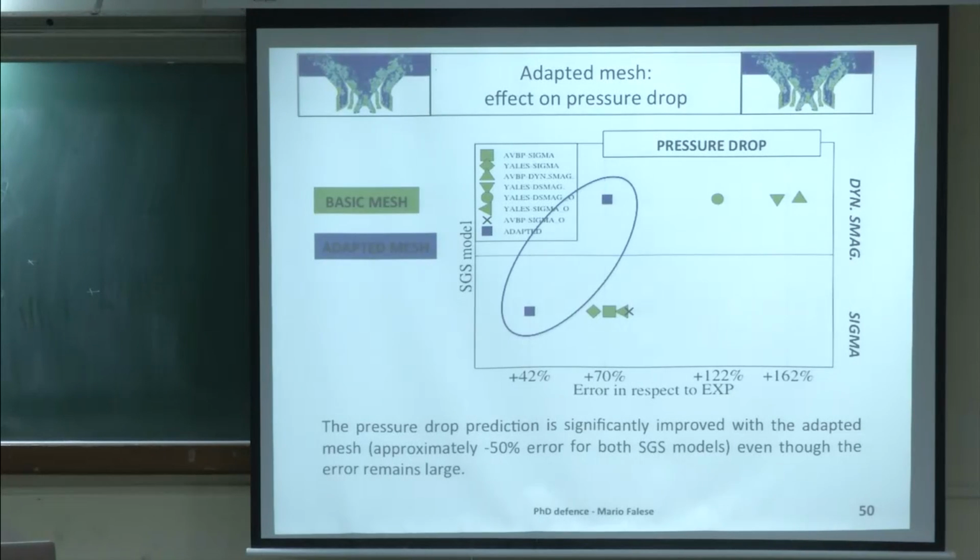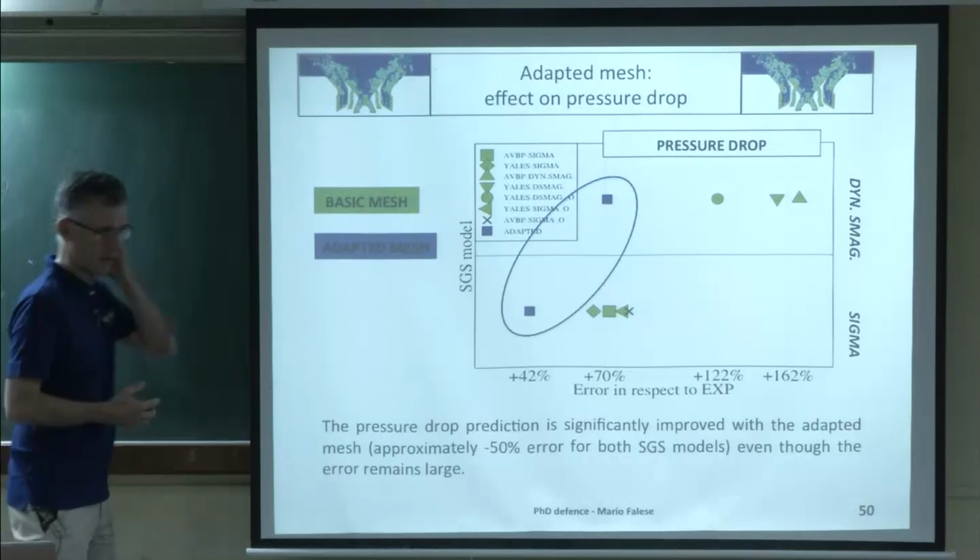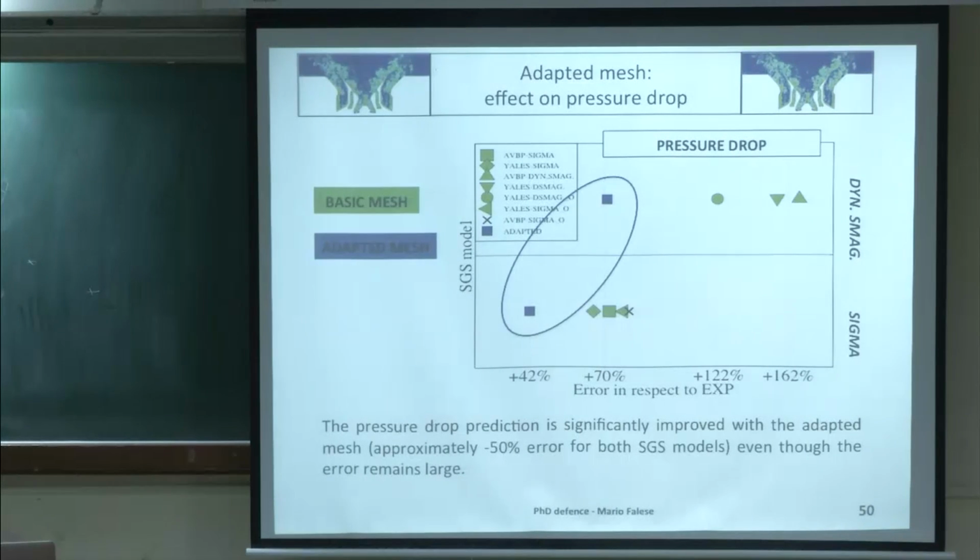Then when you go into the free flow, RANS is completely gone. But here, for pressure loss, they're doing well. And the only way for LES to catch up is to have a good mesh here, because LES does not have all these tunings, all these near wall corrections that you have in RANS. You have tens of corrections. They have been tuned over the years, and this is why they do reasonably well in terms of pressure losses.